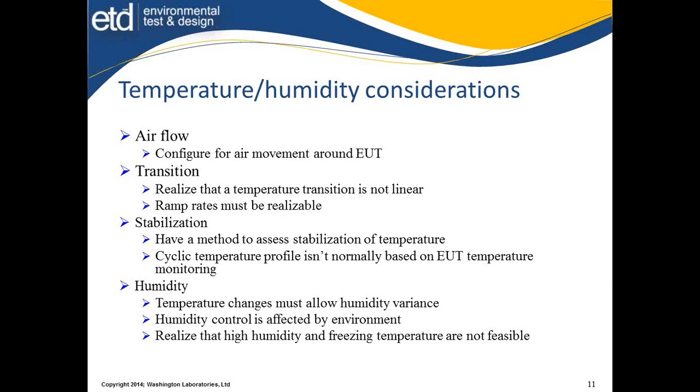Do you have a method to determine what it is? A lot of times the stabilization is based on being at a temperature for an amount of time. The analysis of the mass told us to do that and stay there. We could put in monitoring situations for the unit, but sometimes it gives us a false thing too, where we get a mass that tends to be stable, or it's not changing very rapidly, so we think everything is stabilized. So looking at how we're determining stabilization needs to be part of your plan.